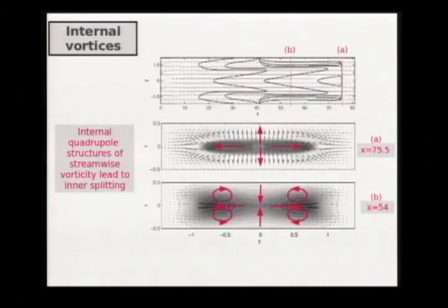This is driven by the presence of a component of vorticity along the direction of the flow. So this is just the concentration contours in the mid-gap plane, and looking at streamwise cross-sections through this area, from these locations, we see that near the tip, the flow simply looks like a source flow, but some distance behind the tip, we find the presence of streamwise quadrupoles that bring fluid from the top and bottom walls towards the mid-gap plane and displace it towards the side boundaries.